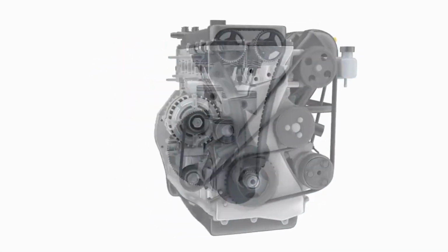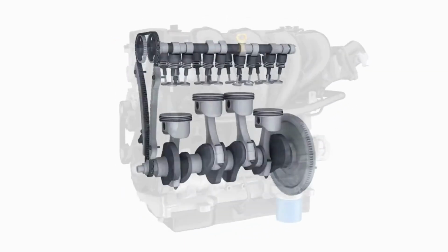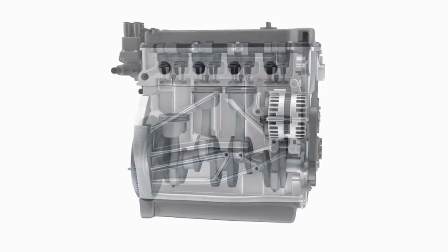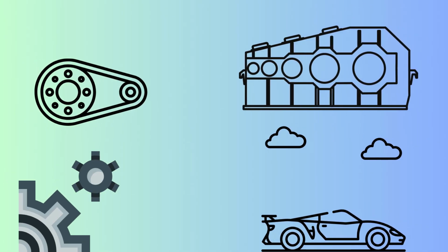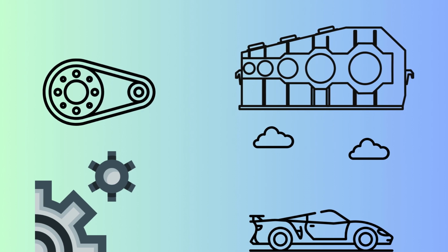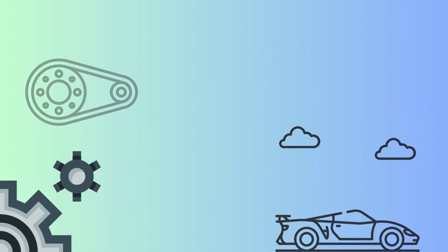A spark ignition (SI) engine produces torque by controlling the net airflow into the engine using throttle, turbocharger wastegate, and cam phasing actuators. 1 Newton meter, Nm, of torque is the torque produced by a force of 1 Newton applied at a perpendicular distance of 1 meter from the pivot point.